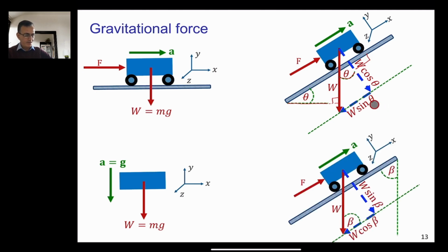And finally, if we have this situation here, that instead of this angle you are given this angle here, the weight is again in the vertical direction. Beta is this angle. If this angle is given as beta, this angle is also beta here. In this case, this side, which is the W y, will become W sine beta, and this will become W cos beta, because this is adjacent and this is opposite to beta.